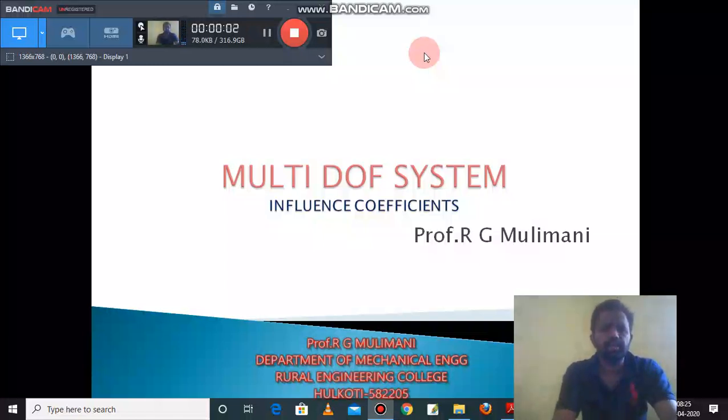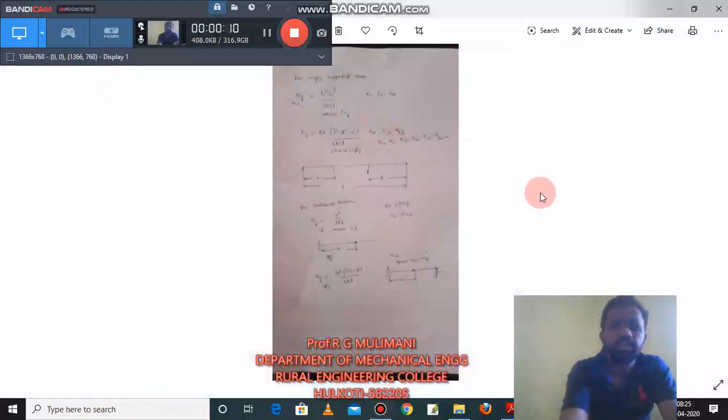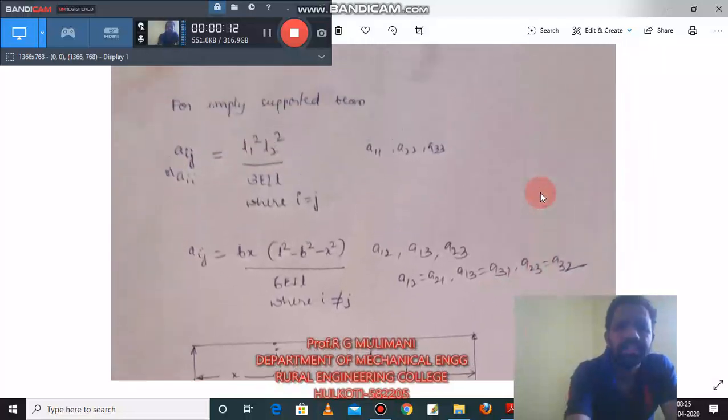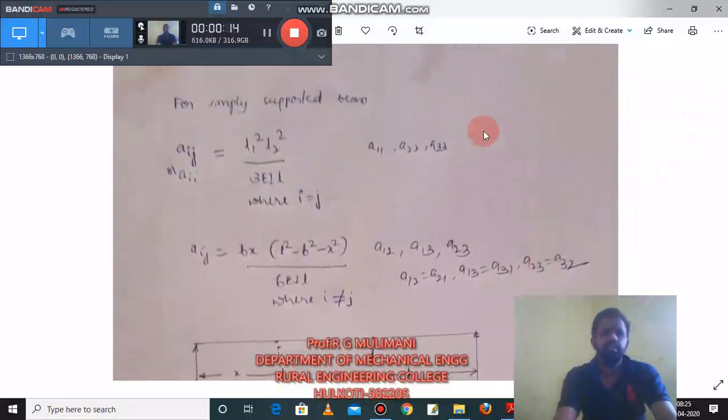Hello, welcome back. In this video session, we will see how to find the influence coefficients for the beams. Okay, for the simply supported beam, to find the influence coefficients, if i is equal to j, for a 3 degree of freedom system, there are 9 influence coefficients, A11 to A33.